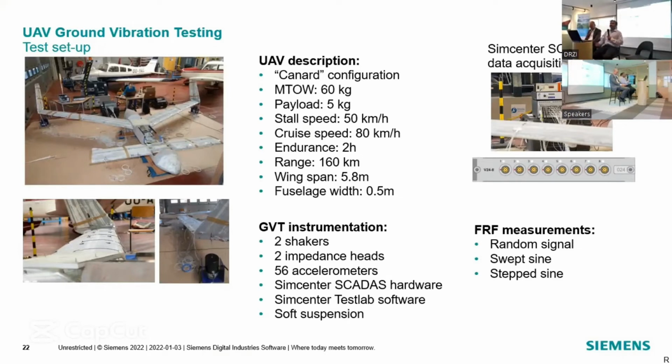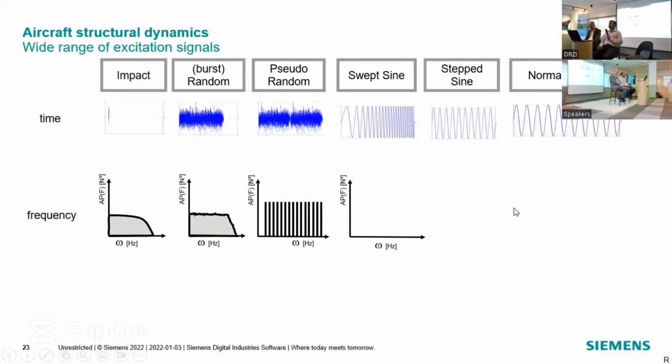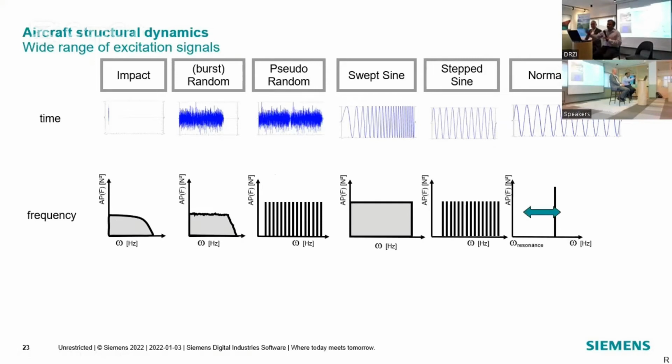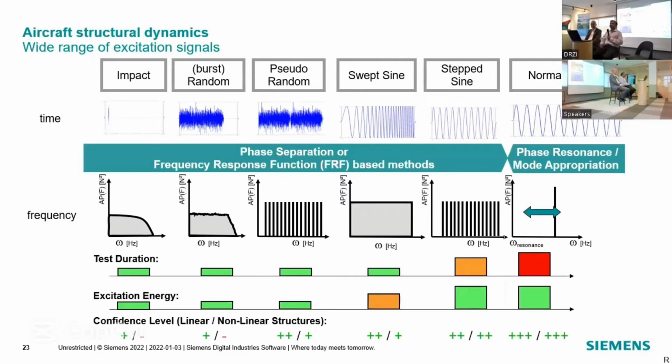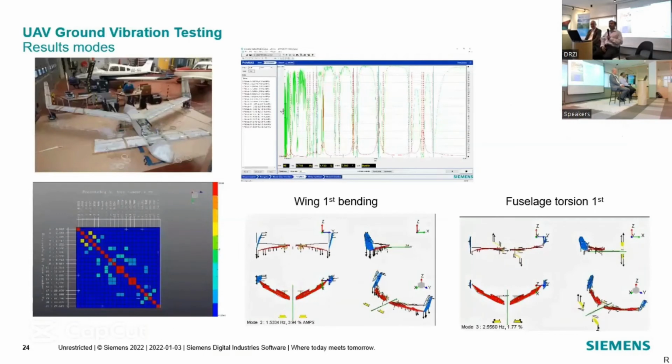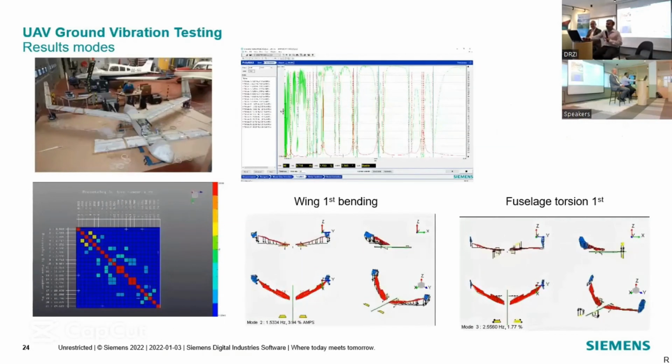Like this, there are a number of test requirements. If you are doing it on the structural side, you need to make sure that the structure is suitable, withstanding sine loads, random loads, and also impact loads and all that. So all these loads can be applied for the structural simulations. Okay. Then this is the place where we compare the results. So we have test results, we also have simulation results, and we compare these two and see why there is a difference and how we can make it closer to the test.